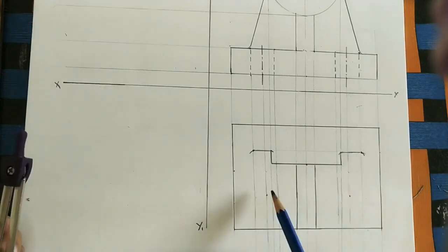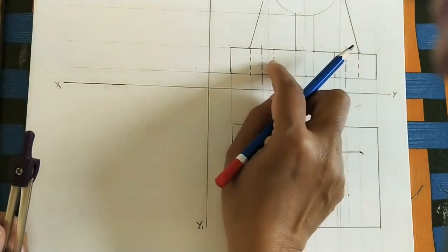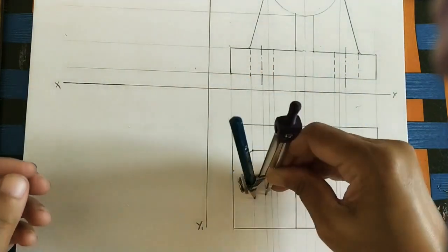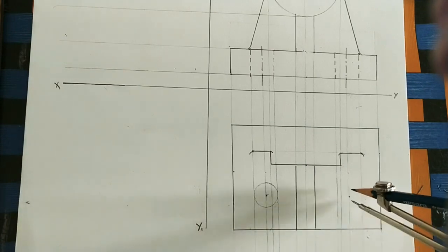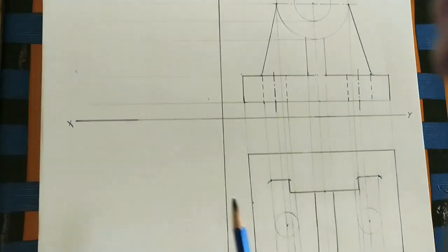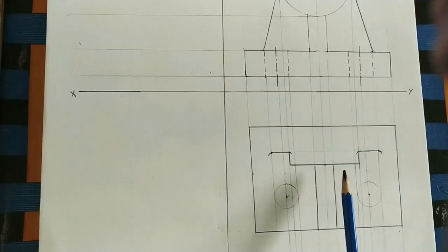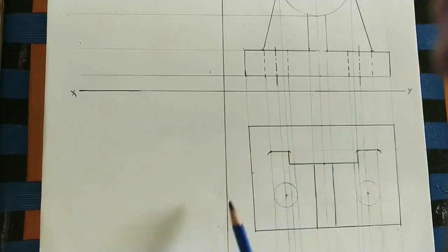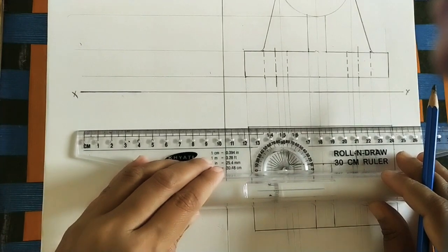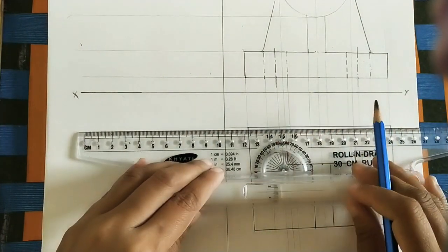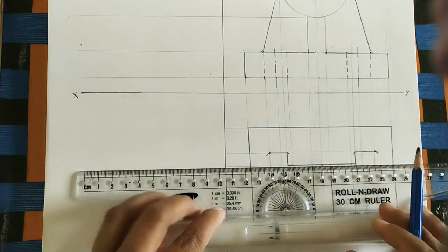After marking the centers, let us do the circles here. This circle should come within this hole, because these are the circles only. Do the circle. Now do one circle here also. For getting the side view, we already did the projectile lines from all the main lines of the front view. Similarly, from the top view we have to do the projectile lines up to this reference line. Already I told you projectile lines mean light color, thin lines compared to the main diagram. From all the main lines we have to do the projectile lines.